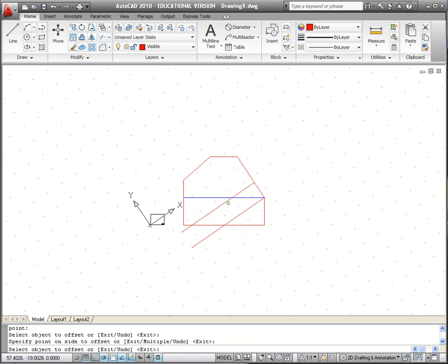That doesn't look right, so let me just double check that. Delete. I can arrow back up to offset. Aha, and then I click something. So that wasn't set to 20. So now I'm going to do that again. And now I've got that line. And then if I offset 10 to either side of this, that'll give me the hidden lines for my hole.